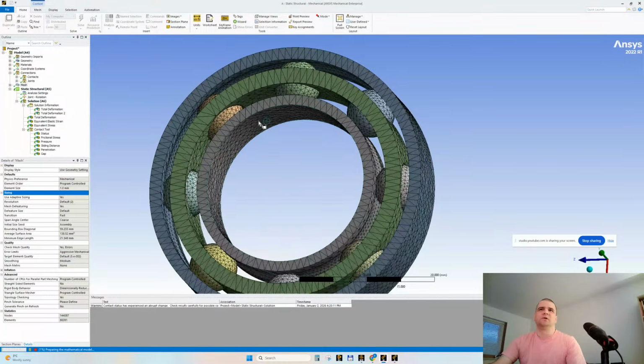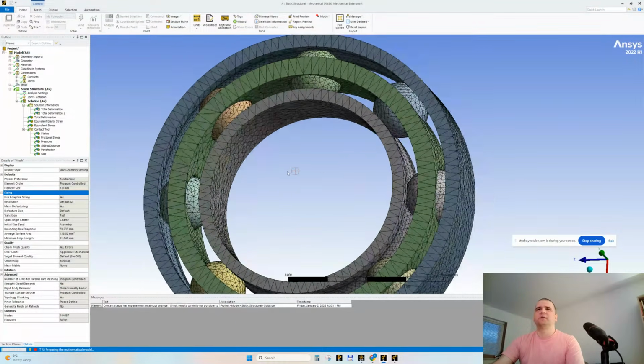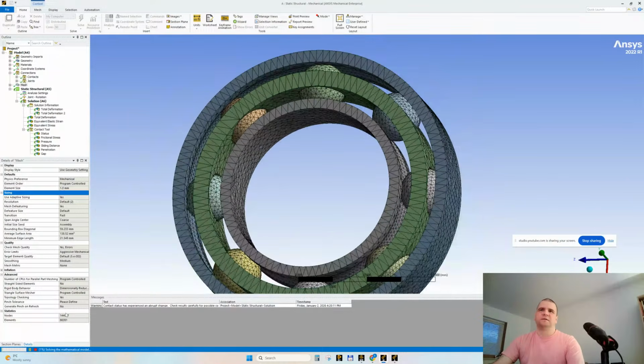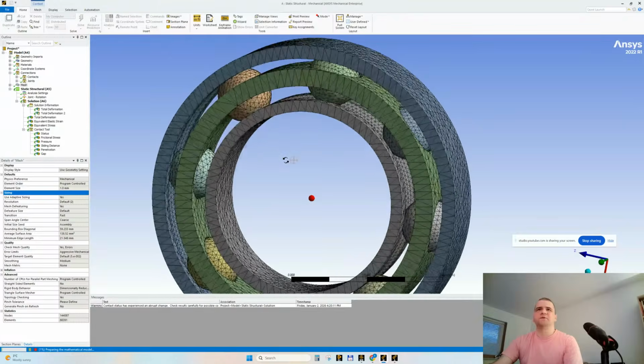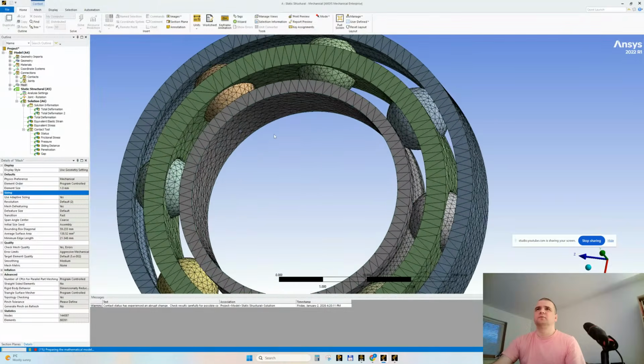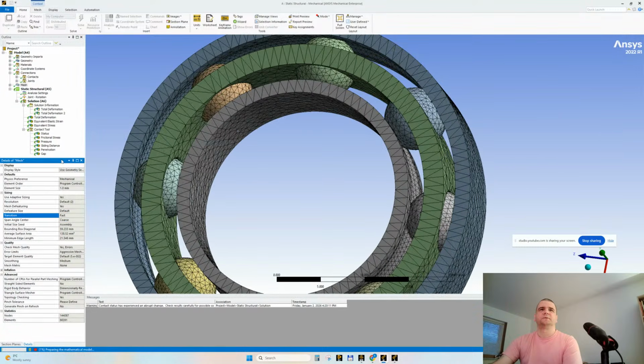Instead, go for a quick, I would not say dirty, for a quick meshing and kind of in the middle, not too coarse, not too refined as you see here, okay? And a very good thing to remember here: fast and coarse. This ensures a fast solving. If you change them to medium or fine, then it will take some time to solve.